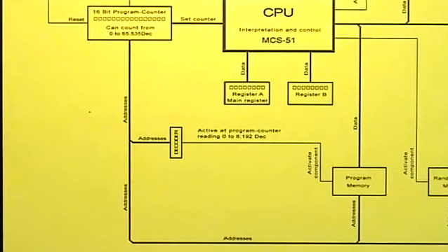These are the two program memory locations that are addressed under program counter contents 1 and 2. The content of these two program memory locations determines the weight of the program jump. Thereafter, the program counter will continue its count with this predetermined counter reading. This is called a jump instruction.